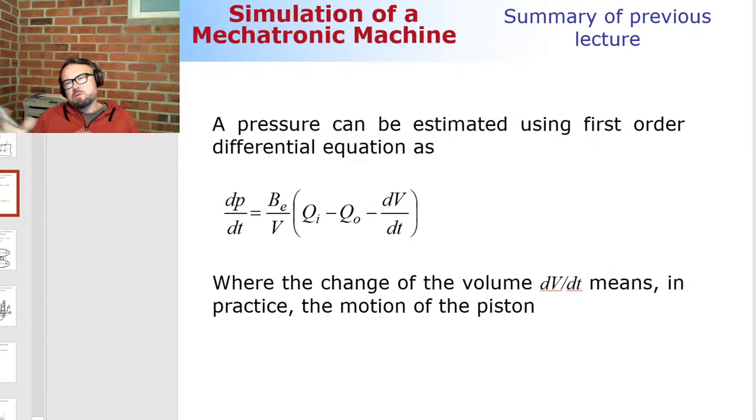We're going to discretize our hydraulic circuit into certain volumes, and within these volumes the pressure will be computed by using a first order differential equation. The first order differential equation is this.